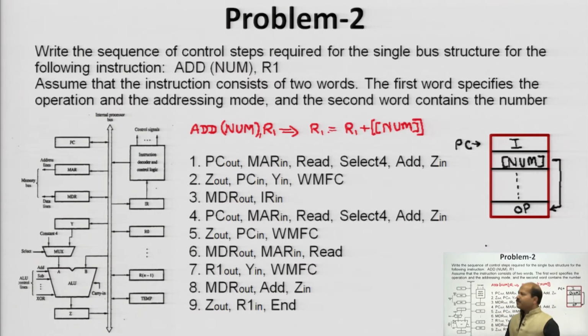In the next problem, this num is the address of the operand. So, we have to perform the fetch operation 2 times. First, we will go to the num location, and in the second step, at the num location we have to fetch the content or actual operand. Now, the bracket shows it is an address. In the previous case it was the value, or the data which was stored in memory. Now, in this particular case it is an address from where we can get the second operand.